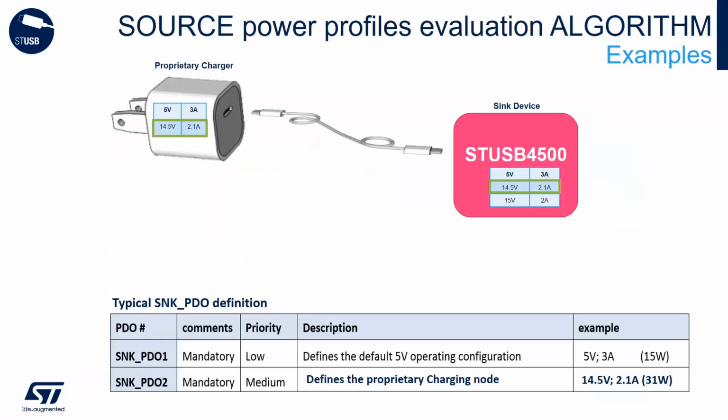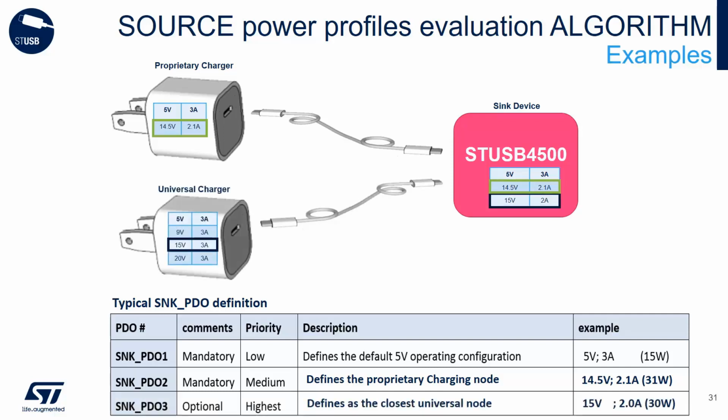The 5 volt at 3 amp power profile is mandatory by the standard, so that is always the PDO0 profile. But up to 2 custom power profiles can also be configured in NVRAM. That enables support for a custom charger as well as a universal charger.